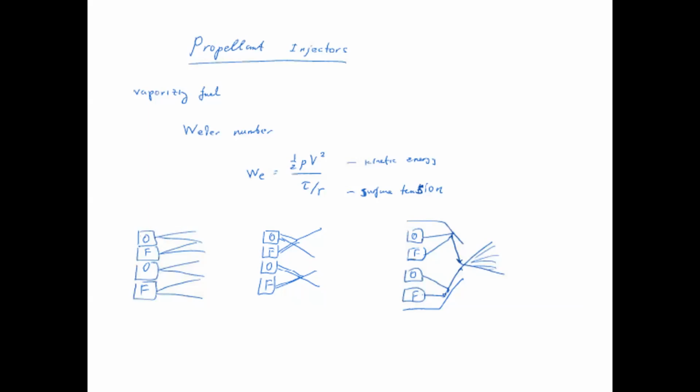So here in the diagrams, you can see there are three different types of injectors. You have injectors basically individually giving out the oxidizer and fuel. And then in the second case, they are basically mixing, and that mixture is going towards the chamber. And then you have a third type of system in which you have an orifice in which the mixing is much more effective. All the injectors, their mixing is properly done, and through the orifice, it goes into the combustion chamber.